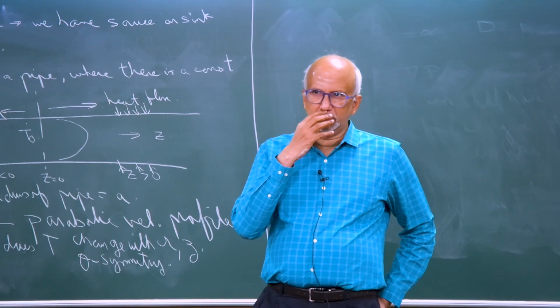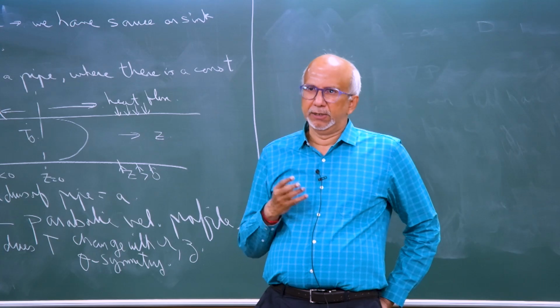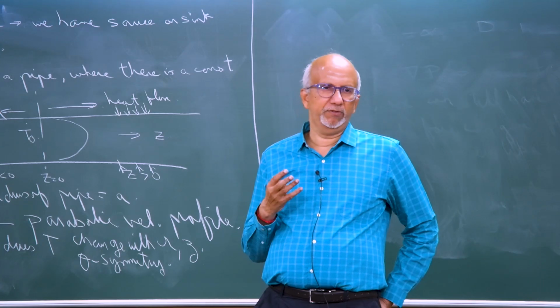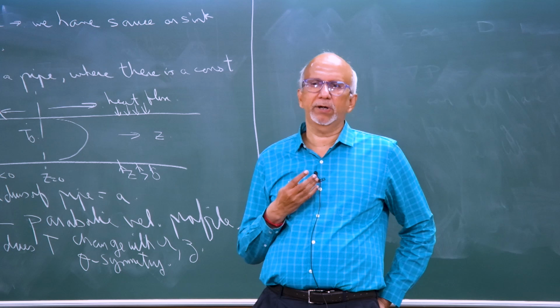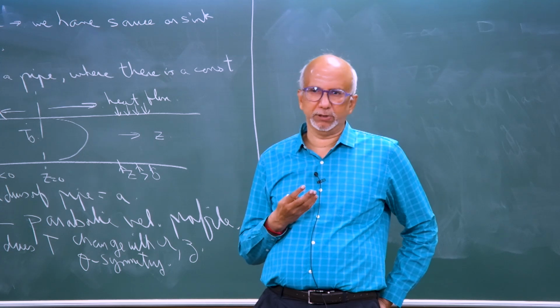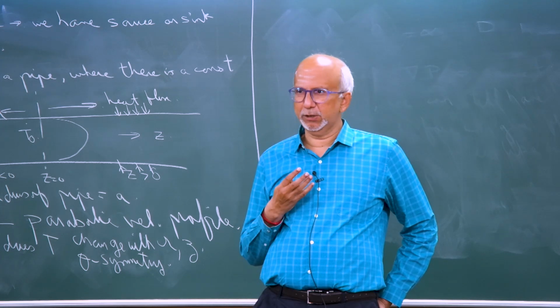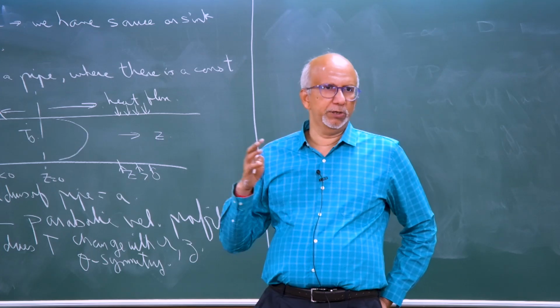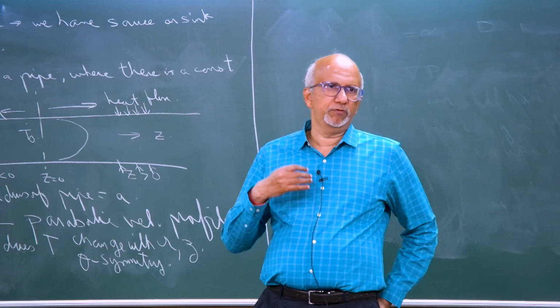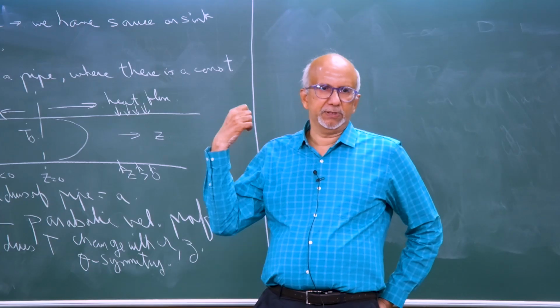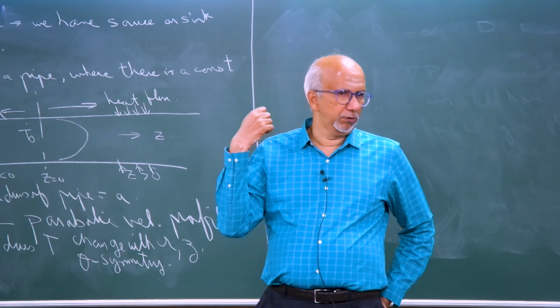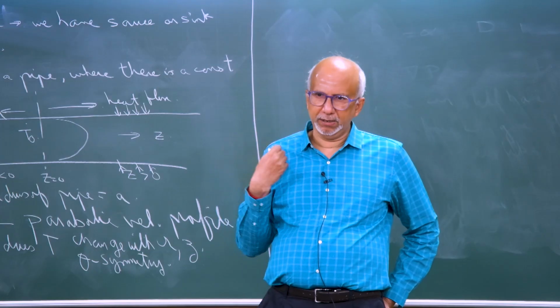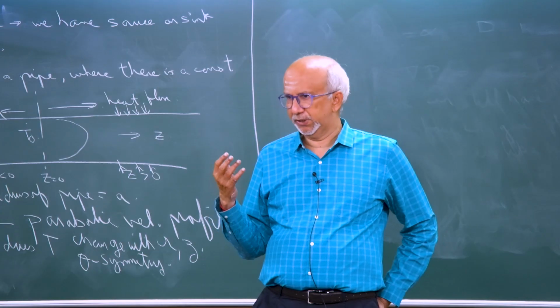The point I am going to make now is, there are 2 ways to solve the problem. You have to be very clear about what exactly is of interest to you, what your focus is, what it is that you really want to find out. So, one way is to include all the effects: put viscosity as a function of temperature, specific heat as a function of temperature, density as a function of temperature, because all of these properties are going to change.